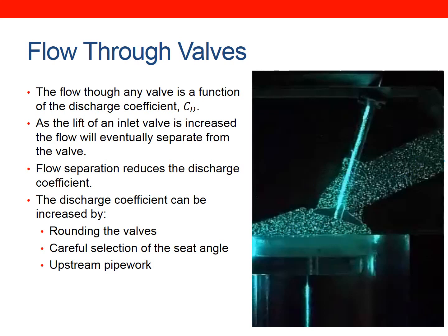There's a laser over here which is shining in this way, and it's illuminating all these particles which are in the fluid. And I say fluid because what's really here in this instance is probably water, some kind of liquid. This is quite a common method for trying to understand flow phenomena in engines. Rather than looking at the air, because it's happening very quickly and it's quite hard to seed it and to measure it, you actually replace the air with a liquid such as water.